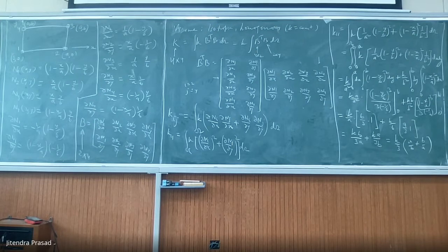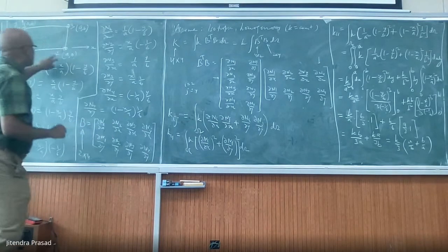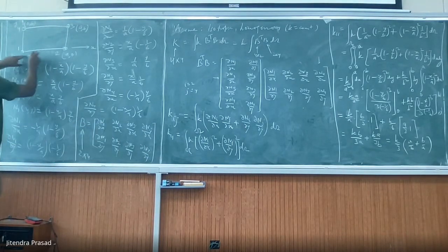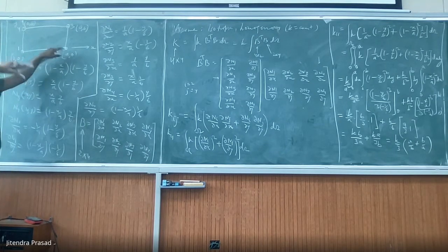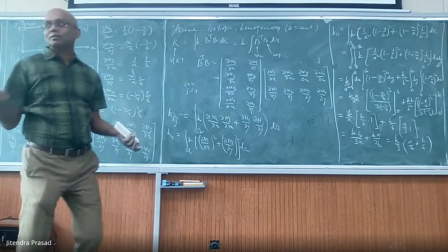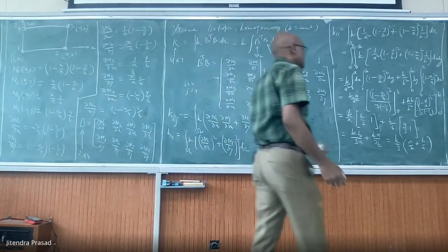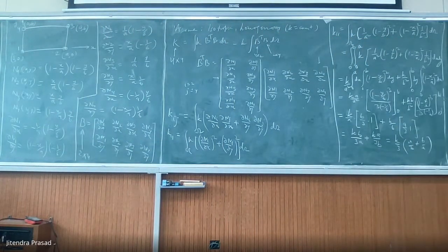The moment you mesh it, and if you have chosen a rectangular element, then what it will do? It will find out what is the value of A, what is the value of B. I mean, what is the width, what is the height of that. Accordingly, it will build the stiffness matrix. That's what it does. So this formula will be already fed in somewhere.